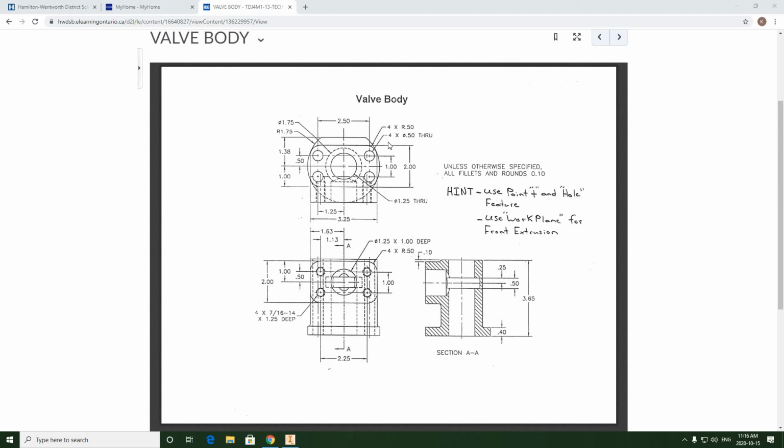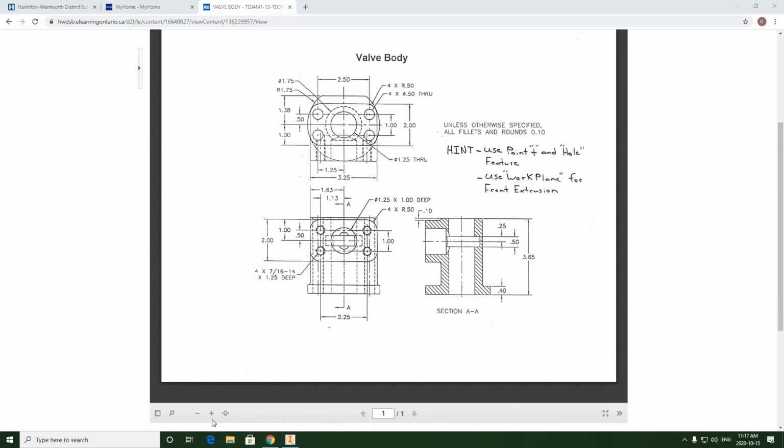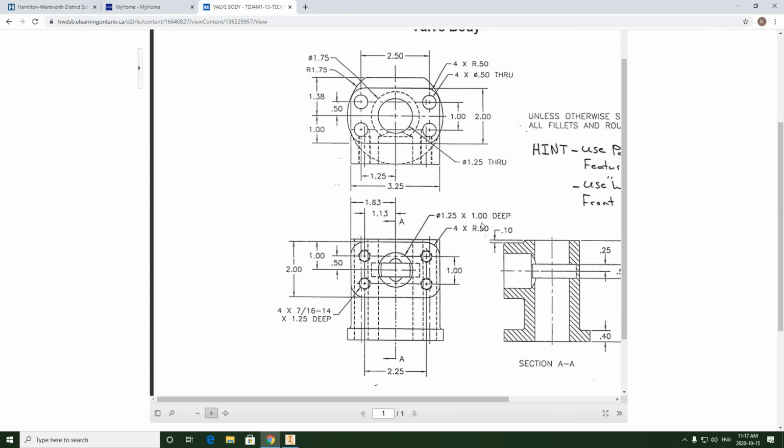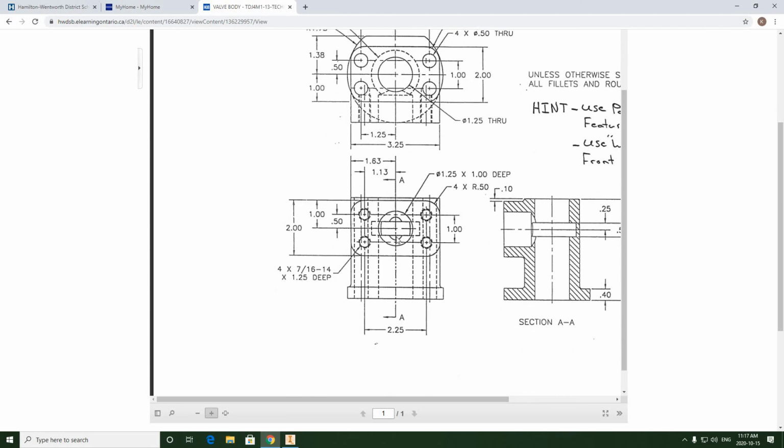Now I'm going to be cleaning up some of this dimensioning. A lot of this dimensioning isn't bad, but it could be placed a little better than what we see here. For example, there are dimension extension lines that are crossing over ordinate dimension lines, and a little bit of unnecessary crowding. And we're going to be improving on how we do the thread and hole callouts on this drawing as well.